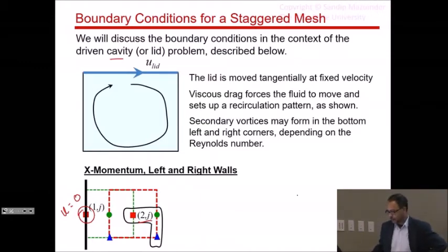All right. So I want to set up the boundary condition for this particular control volume. Okay. Now, it so happens that this control volume, as you can see, is really an interior control volume. It shares no face with the boundary at all. Okay. In fact, it does have a western node, just like any other interior control volume, except that the western node velocity itself is known. Okay. But in terms of developing the finite volume equation, it is no different than an interior control volume because it is actually interior. All right, even though we are thinking of it as a boundary control volume.